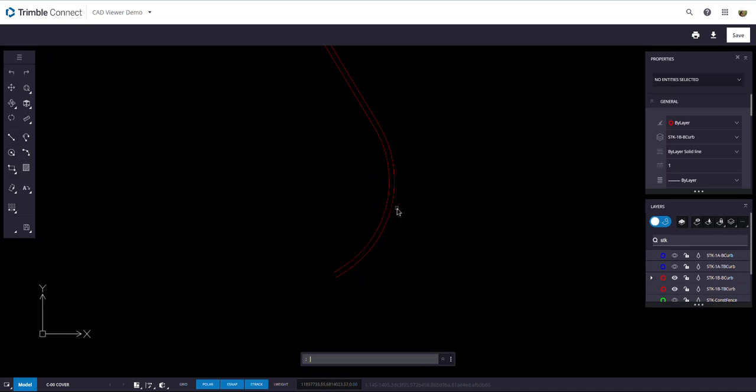All right. So we're going to draw an arc, but before we do that, we want to make sure that this line and this line are, you can see they're lines and polylines. So let's do a P edit. We'll say yes, turn them into polylines. Okay. Then now when we select them, they're both polylines, and we can come up here and change the Z value to 0. Okay. And then we know that this one is 0.